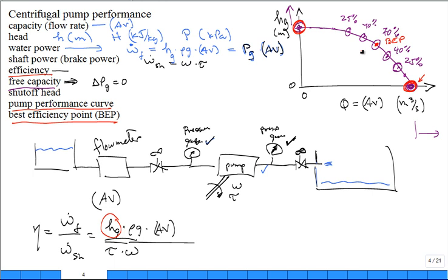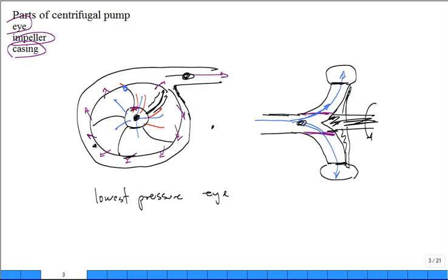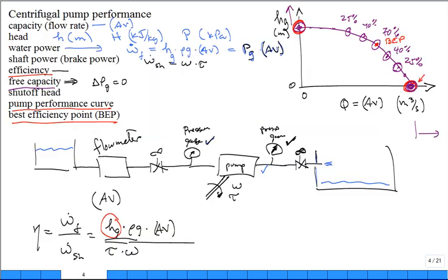I just made up these numbers. All right. Now, as a manufacturer, we were introduced to this idea of impeller and a casing. They like to make a casing and then put the maximum impeller in it and then a few sizes smaller, so that they can sell one casing with different impellers, so it's different models of the pump, but they can have control of logistics, right? Manufacturing makes sense. You have to have all the warehouse, all these pumps and everything else, right? So what they'll do is they'll change the impeller diameter. They'll have a big one, the maximum that'll fit in that casing. They'll drop it a little bit, and they'll get another curve.